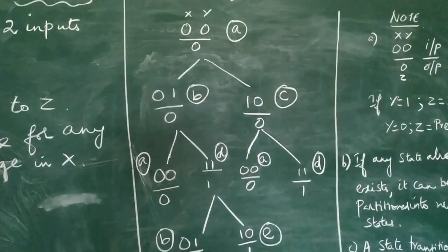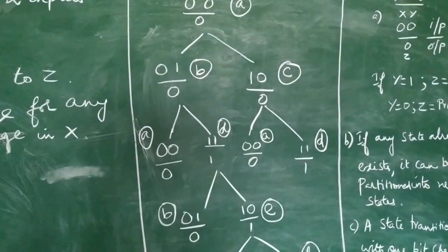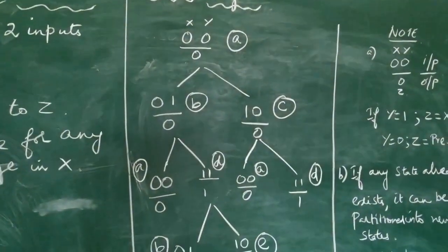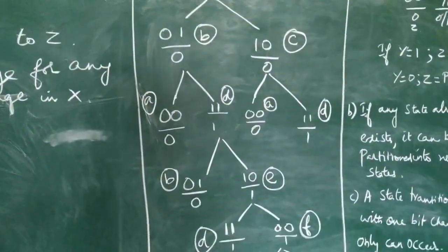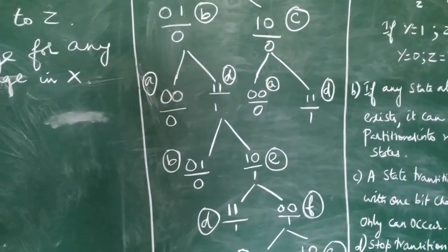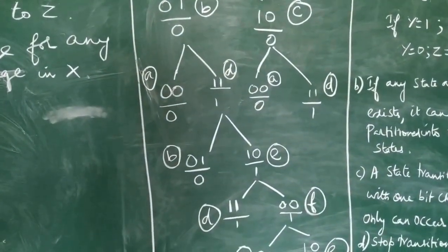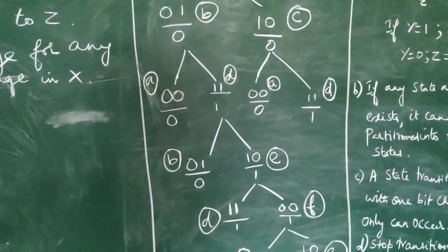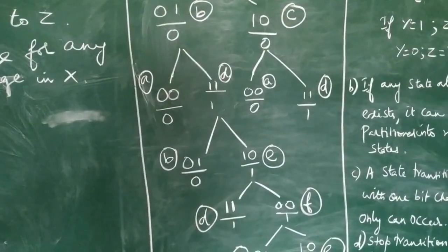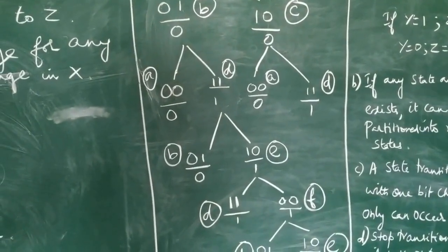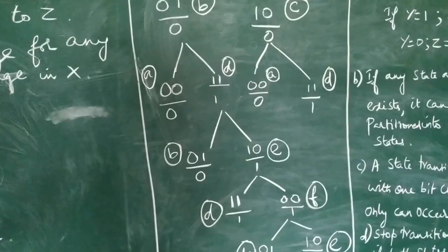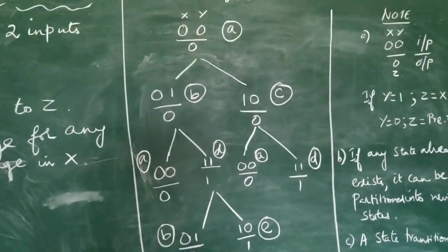Okay. Now here, if you look into the adjacent states, the left hand side it is AD and in the right hand side also it is AD. So we have A is already existing there, we don't partition. D now we had partitioned, transition had taken place to B and E. So now again this right hand side A and D should not be further made to cause a transition. A is already there.